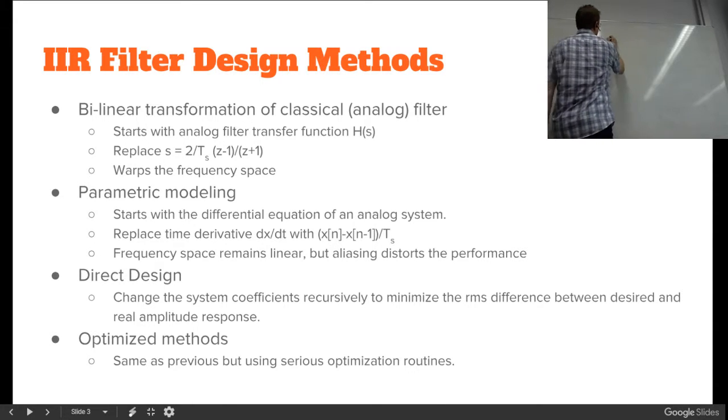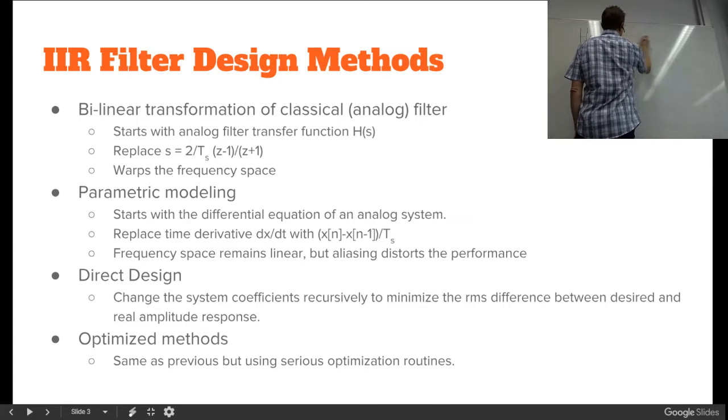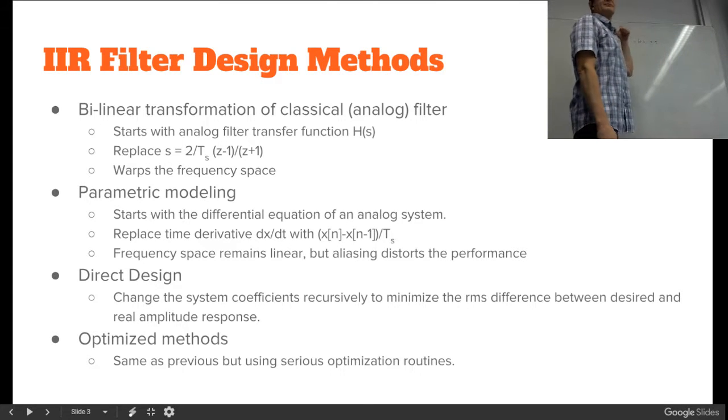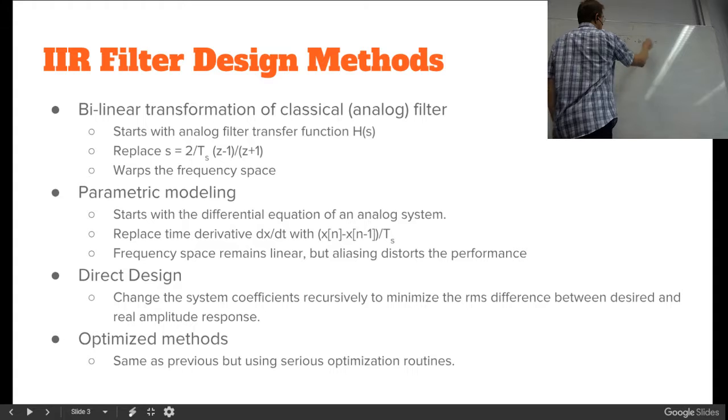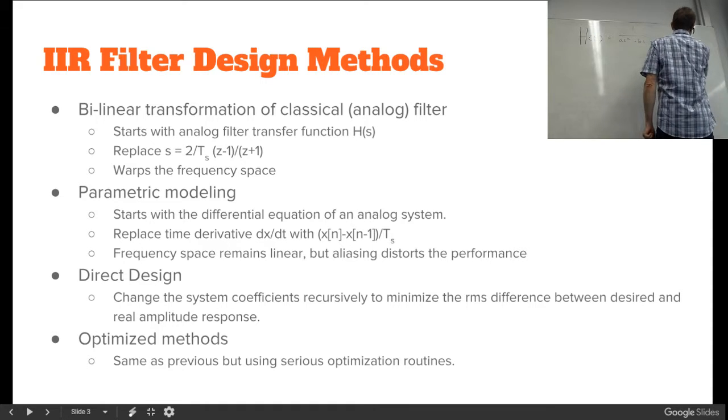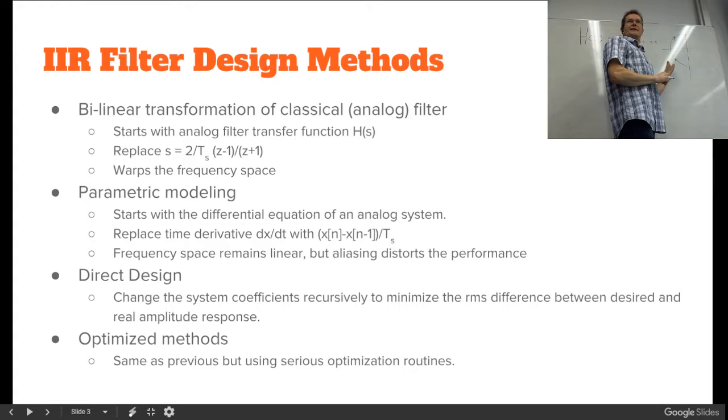For example, for a low-pass filter in the analog domain, the transfer function would be something like that. Like a Sallen-Key low-pass filter looks like that, and you will set the resistors and capacitors such that in the S-plane you would get a Butterworth design.